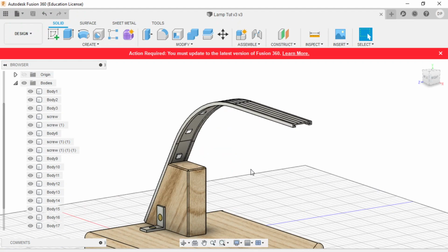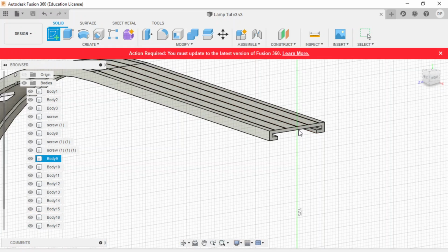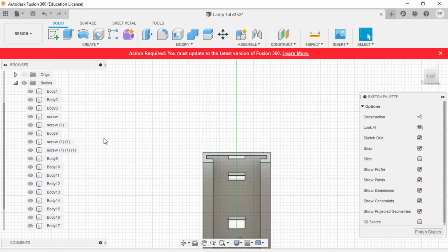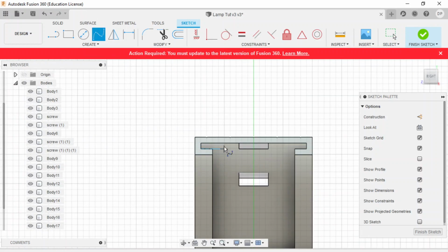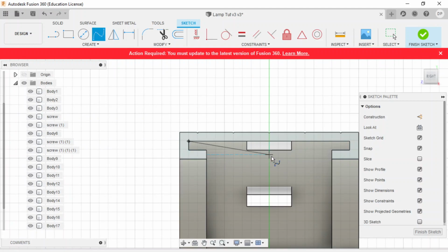Now, you can put a piece of plastic to cover your design. So let's say we sketch and we wanted this plane over here. Let's say we just want to design a quick piece of plastic that goes over the top. Let's say it looks something like this. Let's press enter. I just did a spline.